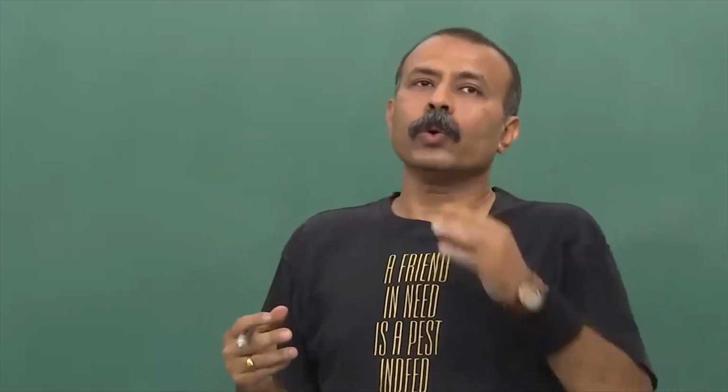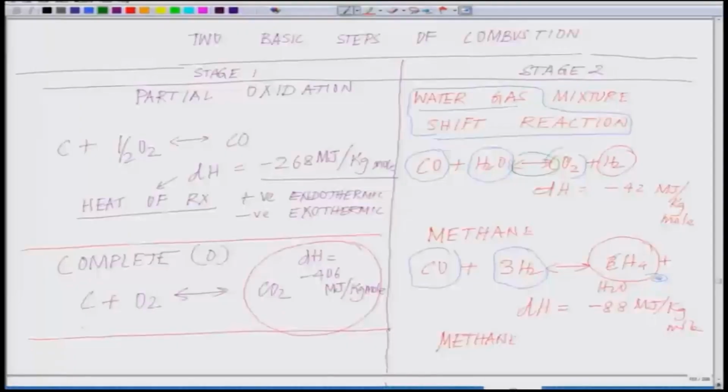So, in other words, these four reactions, if you see the parameters, so water content. If you increase the water, say for example, let us take this, if you increase the water content, there is a possibility you will have more hydrogen and CO2 forming on the right hand side. Similarly, out here if you could increase the carbon monoxide, automatically the reaction will be shifting more towards the methane production, right.